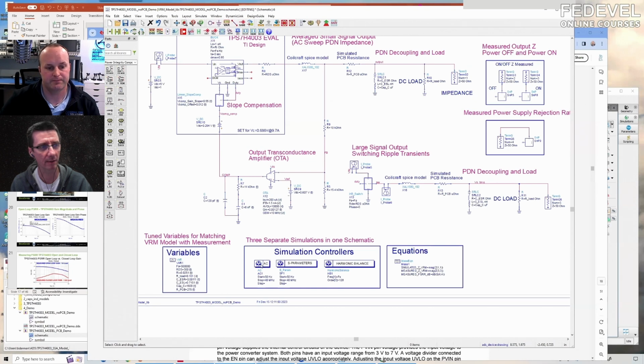This may not be a very clever question: why AC? Why not DC? Oh, well, remember, when we talk about PSRR, you're sweeping the frequency. DC is only one component of frequency. You're only looking at one frequency point. If we want to plot the PSRR, we want to plot it for all the frequencies. So we need AC to see the response for all the frequencies.